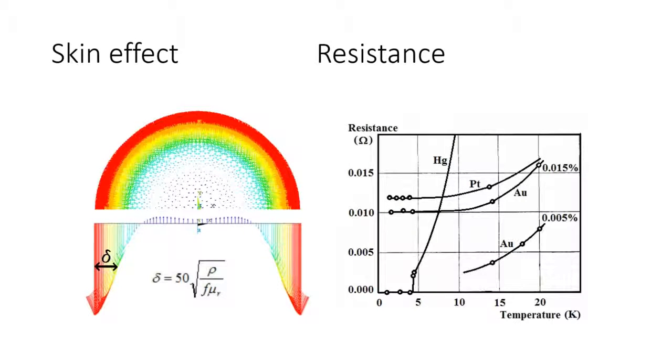The AC current is most frequently used for resistance heating in the industry, and this leads to a non-uniform current distribution in the workpiece due to the skin effect. So as we all know, the incident current produces a changing magnetic field. This field produces eddy currents in the material, and these eddy currents are oriented in such a way that they partially cancel the incident current, mostly on the interior of the conductor. Therefore, most of the current will be in the skin zone or the exterior zone of the conductor.